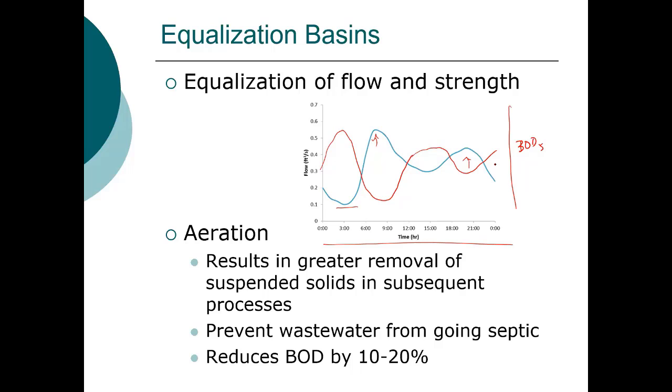Often, aeration is accomplished in these equalization basins, and that's to, one, try and keep the suspended solids in suspension. You don't want that wastewater going septic, so you don't want it to be devoid of oxygen. With aeration, you will get some reduction of BOD because you'll actually get some microbial activity.